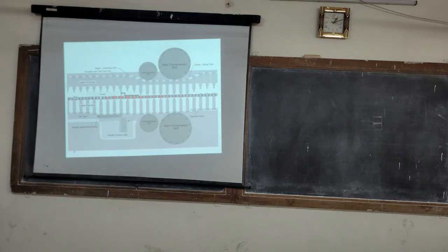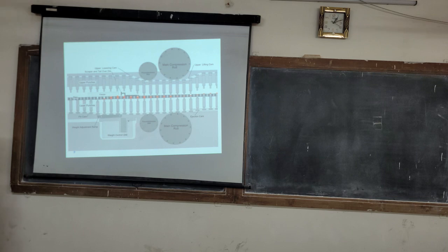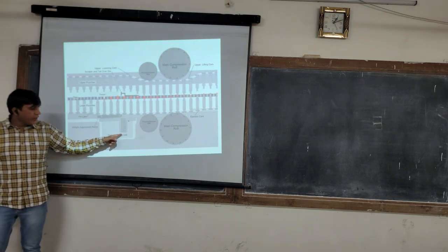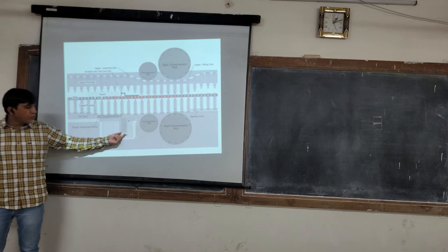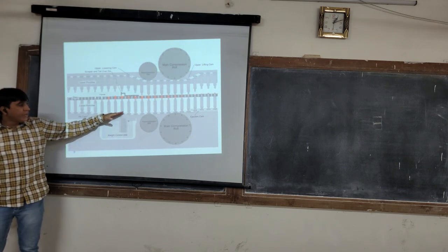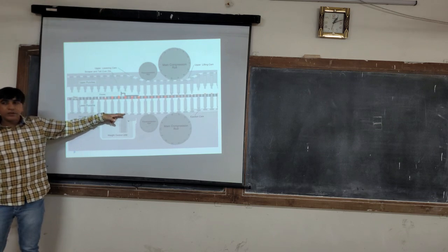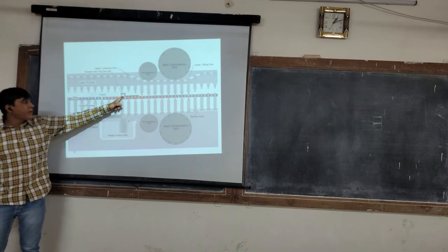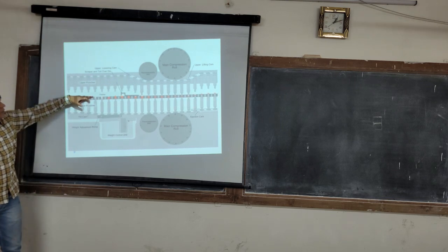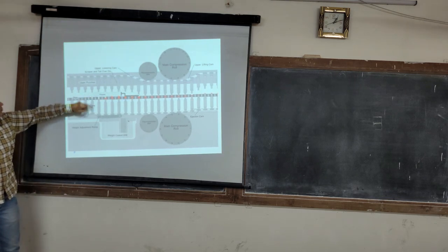This is an animation which shows the compression cycle. This is the weight adjustment ramp and this is the weight control unit. We can rotate this screw and move the position of this ramp. So if we raise it further, the blend will rise. This is a scraper. This will remove extra granules. This is a feeder or feed frame.